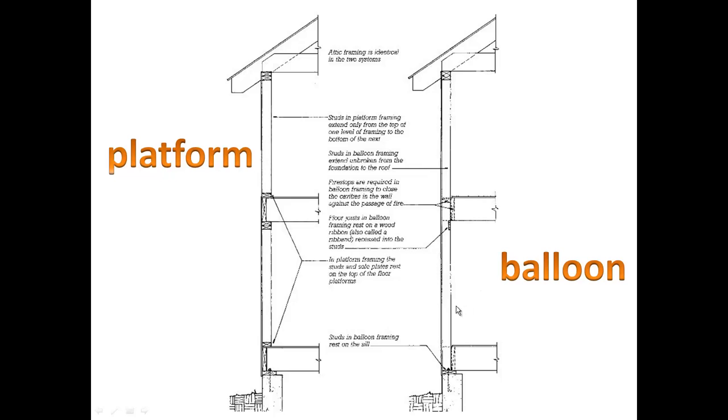And the walls themselves had a tendency to be fire spreaders in that they formed chimneys. So blocks of wood had to be put in between each stud on the way up at the floor levels, called fire stops, to keep that draft from creating this high fire danger. So as it was developed,